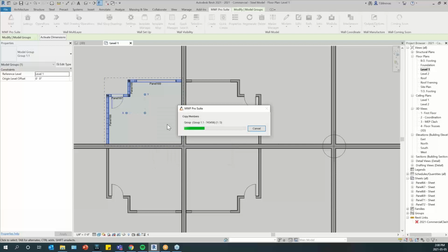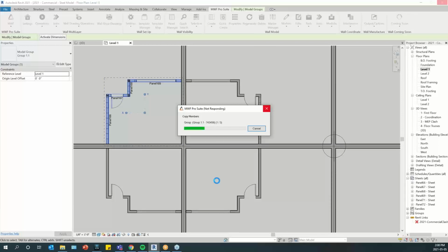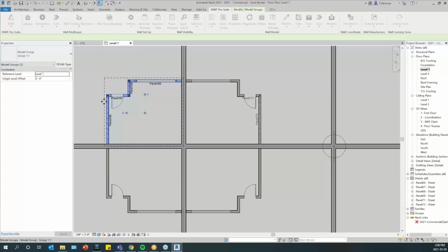If it's unchecked, it will just create the panels, but they will not have any relation to the first set of panels that I have here. So this will not be a parent, and these will not be children of this parent. If I check that option, these will be the parents, the other ones will be children, and they will be locked. All the children will be locked, and in case you have to make some changes to your panel, you will have to unlock the panels.